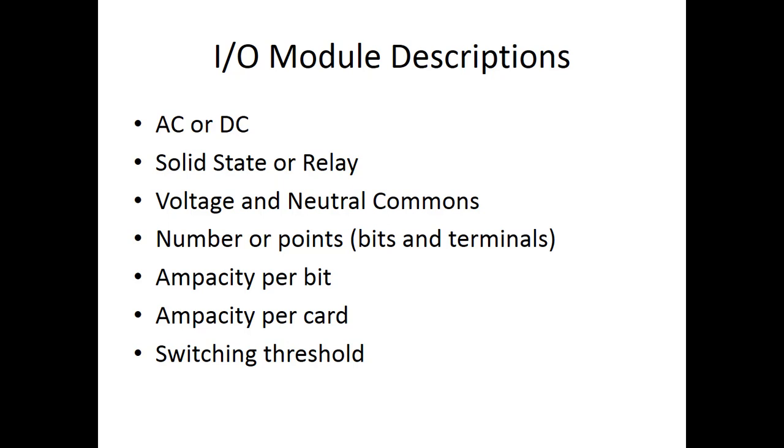And then the switching threshold: you need some voltage coming through there. If you get a little bit of voltage, it might signal the card. We're going to look at that in the lab this time, but you definitely want to be sure that you get the right voltage, so you're not just hitting the threshold, you are getting a true signal instead of just something that activates the card.